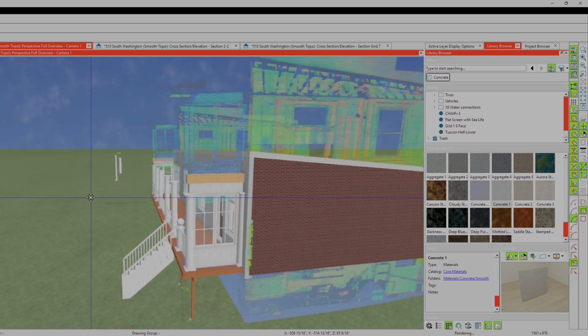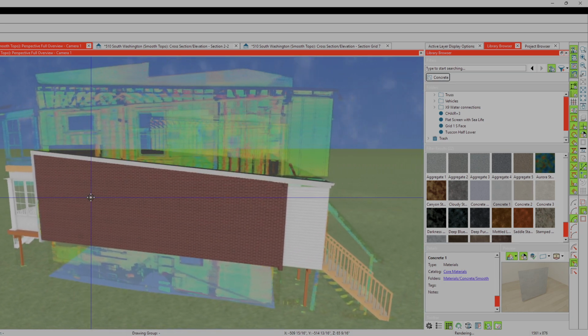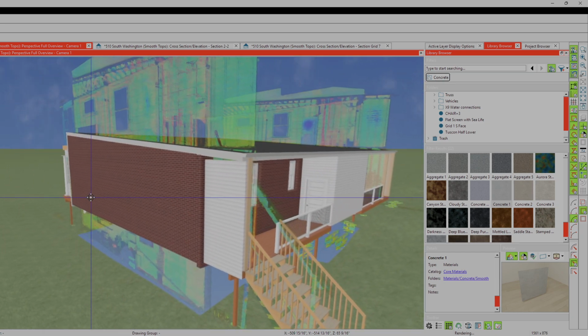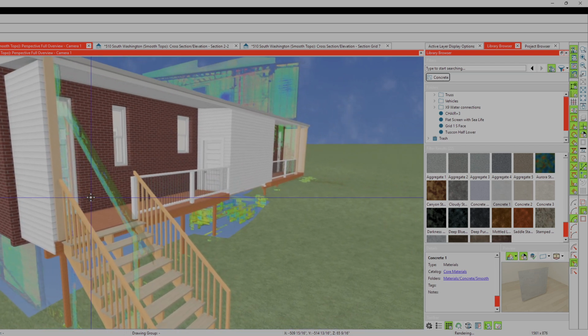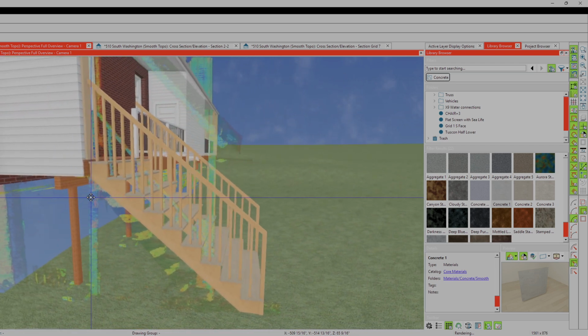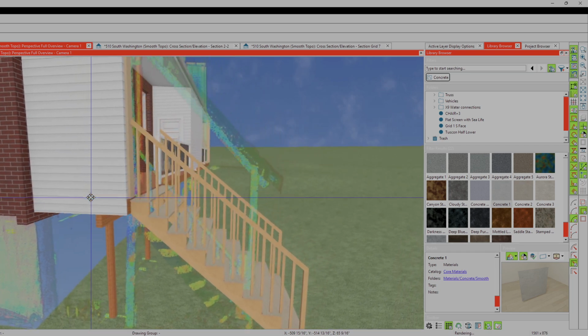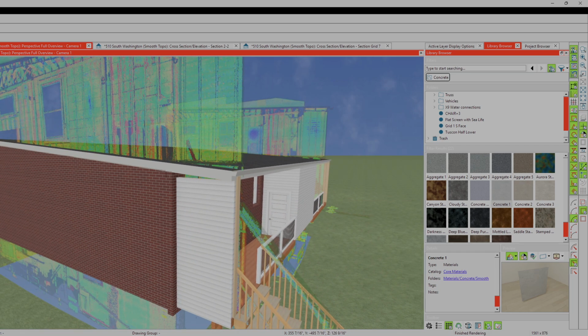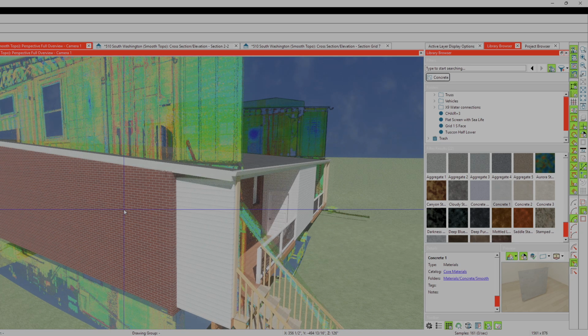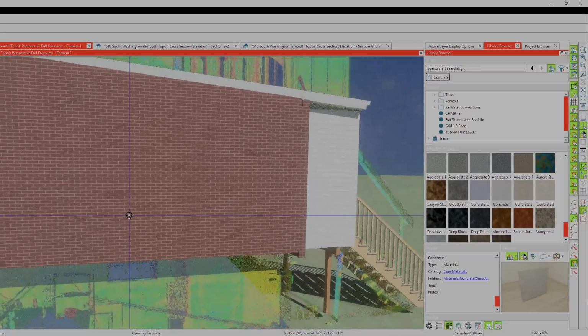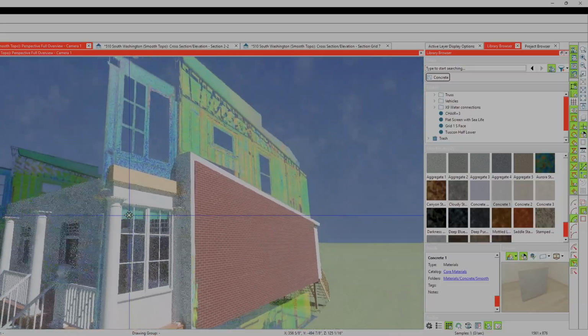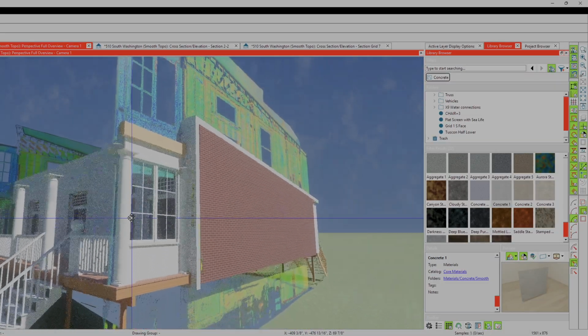in that I can actually see, because it's a material that's applied to a section, I can actually see this image in 3D. Now it's kind of a little ghosty here, but if I go up and I change, and you can't see this because it's off screen on my larger monitor, but I'm switching my rendering style to physically based ray trace, and it gets a little nicer. Now you get this kind of grainy effect when you're moving, but if you wait a second, if you've got a decent video card,